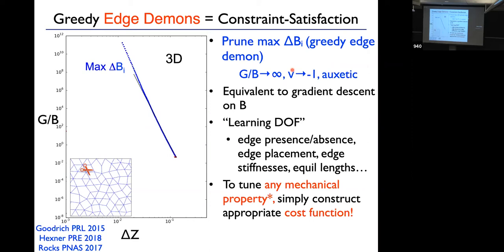And remember that a 0 Poisson ratio, which of course is why cork has a Poisson ratio near 0, which is why it's useful for corking wine bottles. So that's above this dashed line. The Poisson ratio is negative. And when this ratio goes to infinity, the Poisson ratio goes to its maximally negative value of -1.